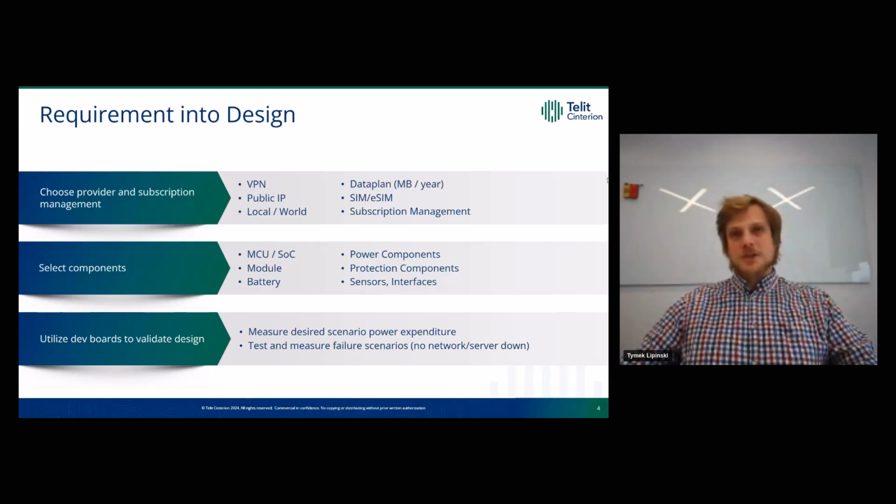Then we select protection components: ESD, surge, EMI interference, all of that has to be covered. And last but not least, sensors and interfaces, because our device has to do something besides connecting to the internet. Once we have that filled in, we need to find our dev boards and utilize them to validate the design.